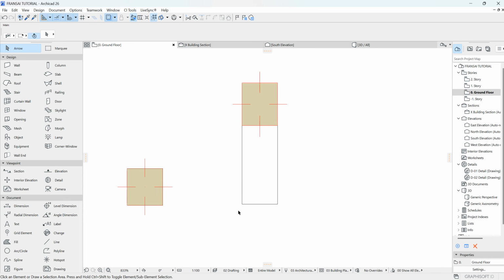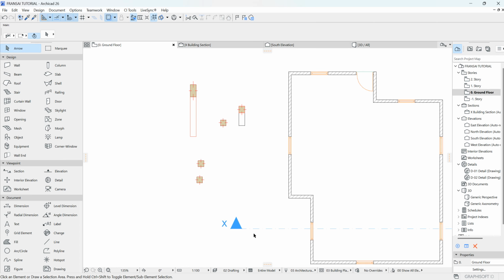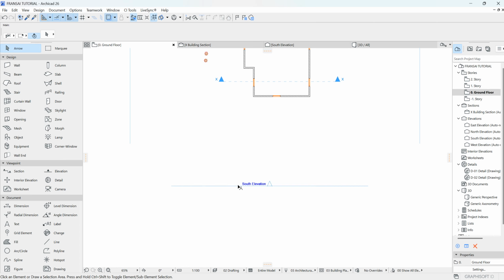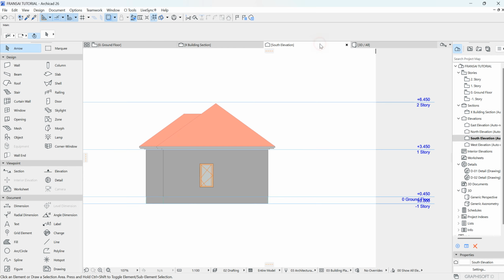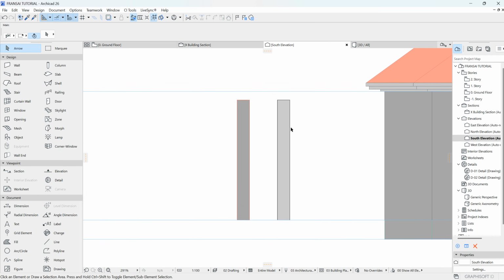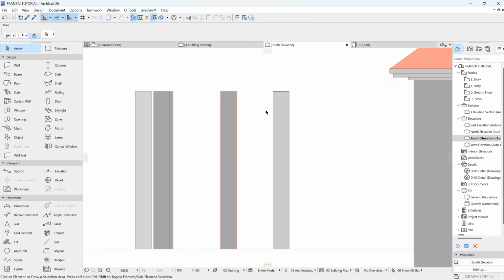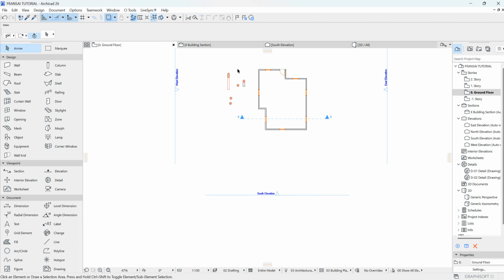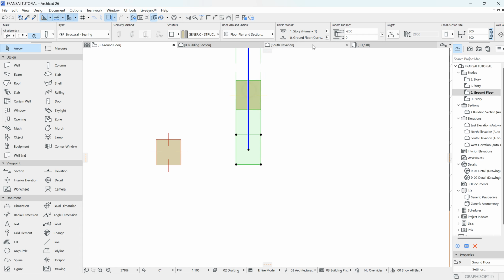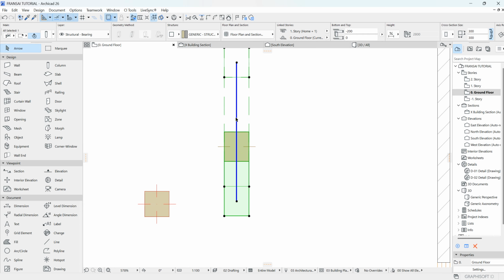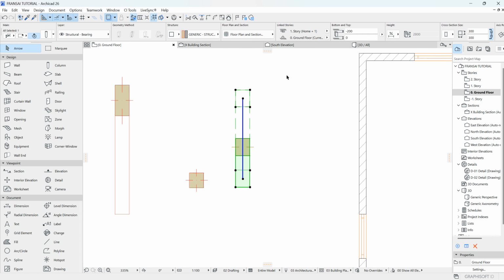Okay, you can see that this is the outline on the elevation. The same thing if I view it on elevation. Okay, let me get my elevation. If I view it on elevation, you now see that it's black while the others are red. So these are ways you can override the materials or the graphic symbols of the column too.